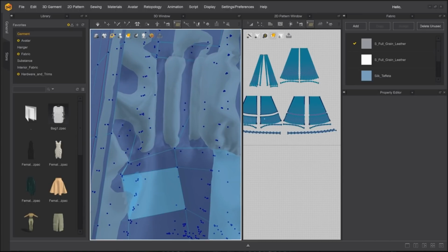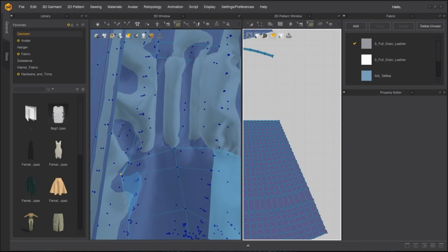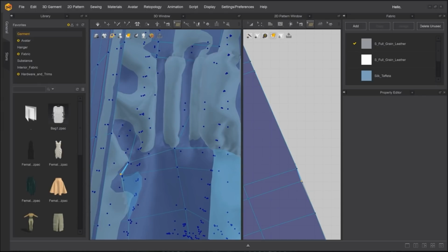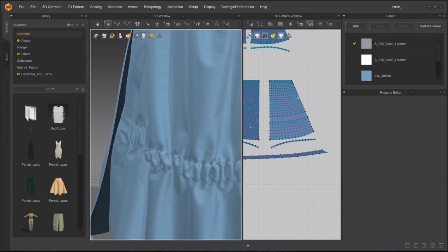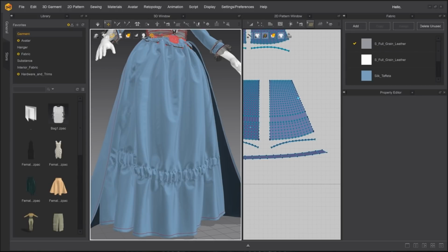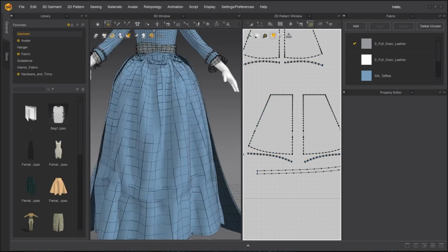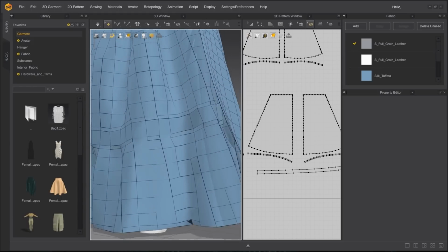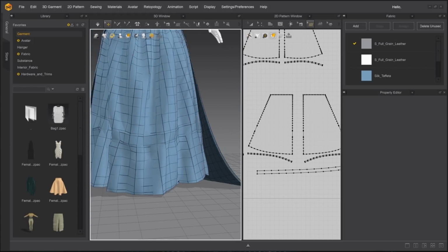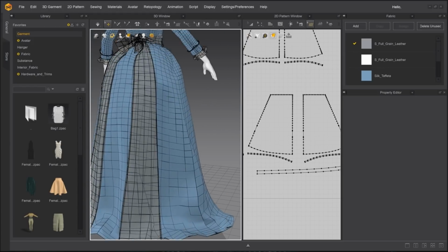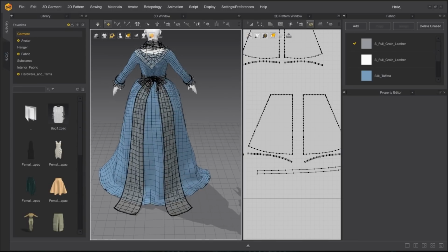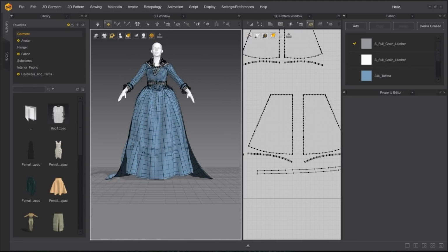Most of the previously misaligned points now match exactly. There are just two that need to be popped back into place, so I snap them to the ghost points they should match with, and I am nearly done. After selecting Remesh All Replace one last time, all vertices along seams are properly set up for welding, and this dress is finally ready for export.